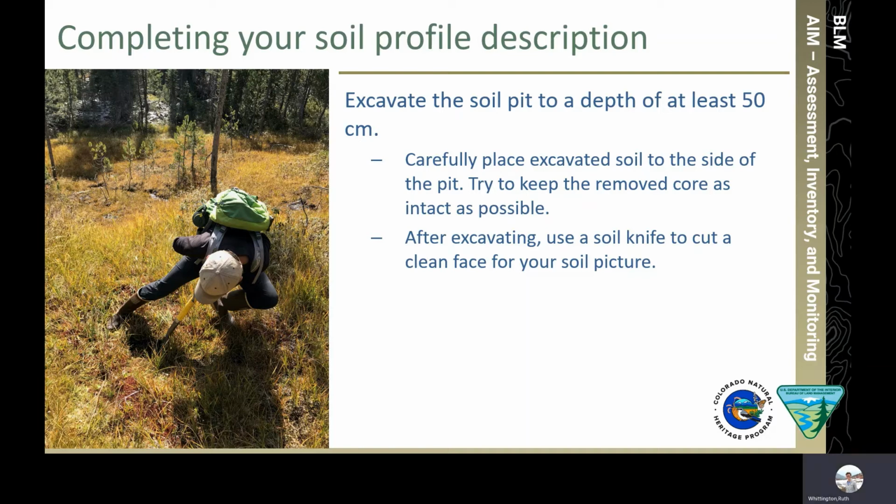It is recommended that you try another soil pit in another location if this first soil pit falls short of the recommended 50 centimeters. Once you have a soil core removed, cut or shave a clean face of your soil profile away from the soil face before taking a picture of the removed core.